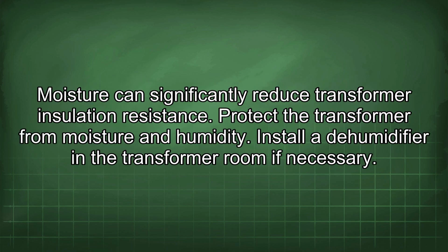Moisture can significantly reduce transformer insulation resistance. Protect the transformer from moisture and humidity. Install a dehumidifier in the transformer room if necessary.